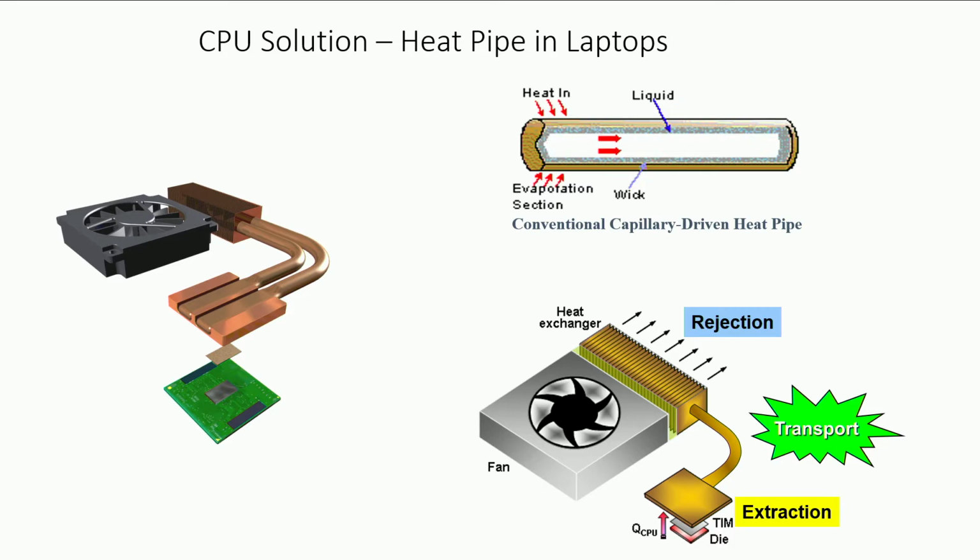So any questions on how a heat pipe works? Very fascinating technology, of course now very mature and almost everywhere. I think Apple computers have heat pipes of about 1 mm thickness. You said that they're not at ambient pressure inside? No, they are sealed, absolutely. And there are no failures of that? No failures. You can see how it is evacuated and then crimped at the end.